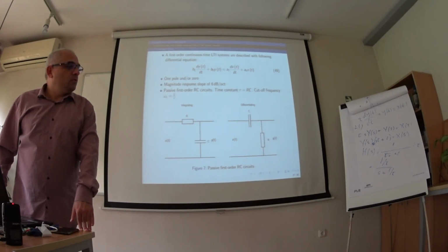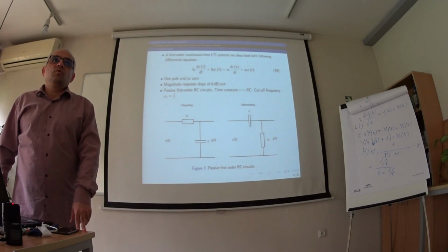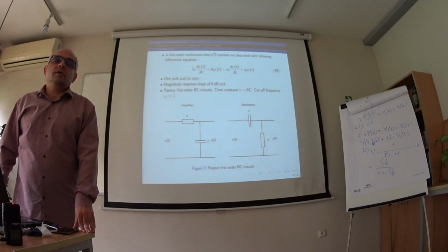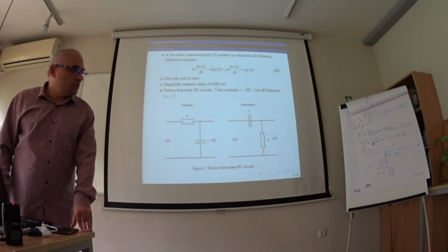We don't want to solve differential equation. We can transfer them with Laplace transform to algebraic equation, and we can analyze the circuit, and we can get back the voltage and current in time domain just by applying the inverse Laplace transform using the table.